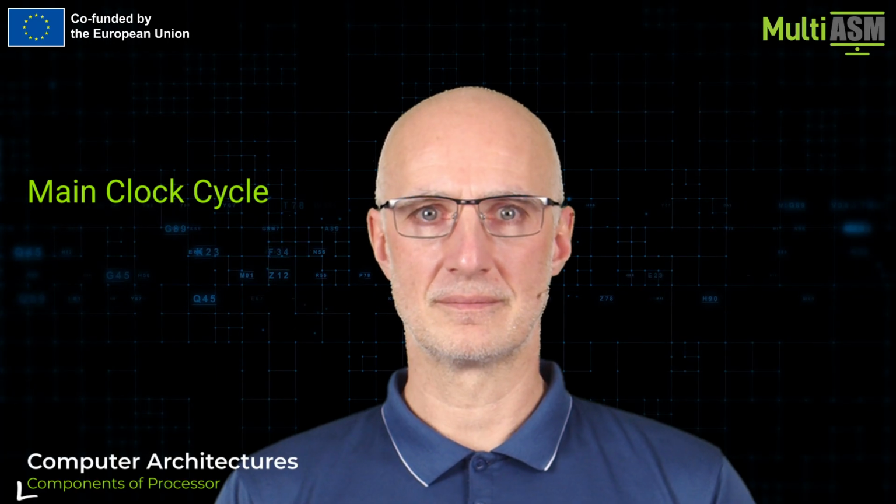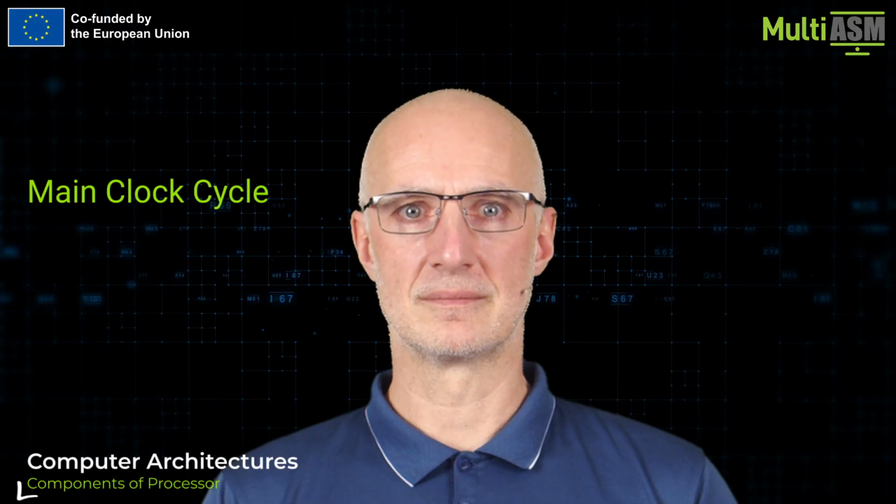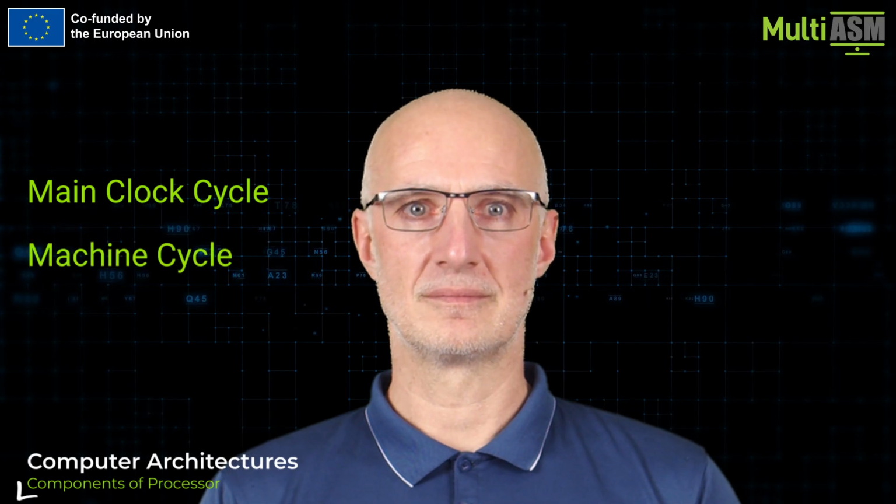The control unit operates according to the clock signal generator cycles known as main clock cycles. With every clock cycle, some internal operations are performed. One such operation is reading or writing the memory, which sometimes requires more than a single clock cycle. Single memory access is known as a machine cycle.